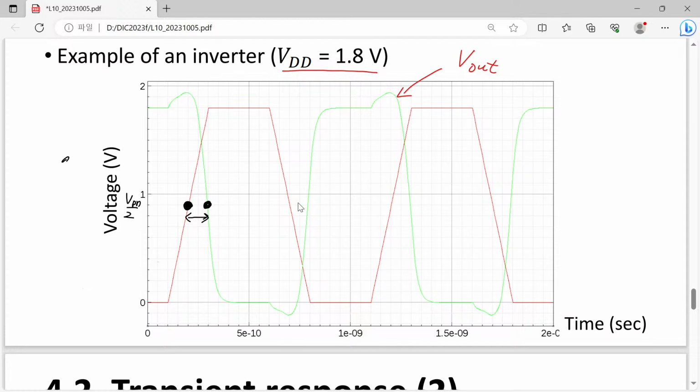Then please also try to find out the falling case. This is 1 and this is the 1, and you can see that here and there you have a distance. So simply speaking, in this case, both your rising propagation delay and falling propagation delay are more or less close to 0.1 nanosecond, because here two interval units correspond to 0.1 nanosecond. So now you can understand the propagation delay of this one. I think that this is really an unloaded one, corresponding to 0.1 nanosecond.